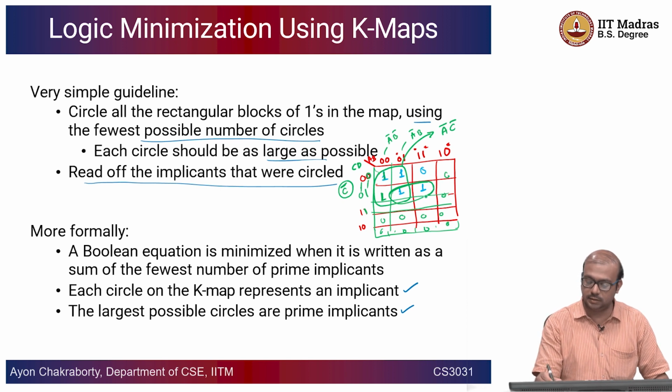Here if you see the other circle that has these 2 components, here you have one entry which is A bar B and the next entry is A B, right. So one is A bar B and the other one is A B. So as you can very clearly see, B remains unchanged across these 2 things. A bar and A get unified and eventually vanish.